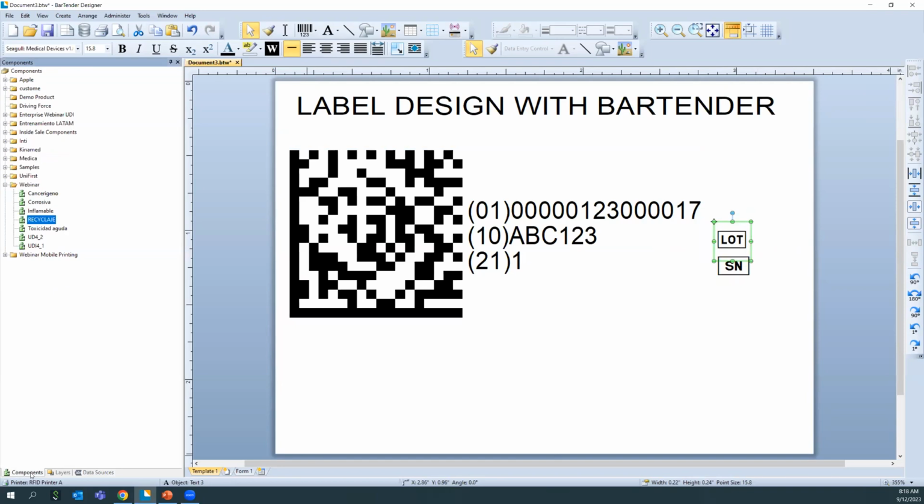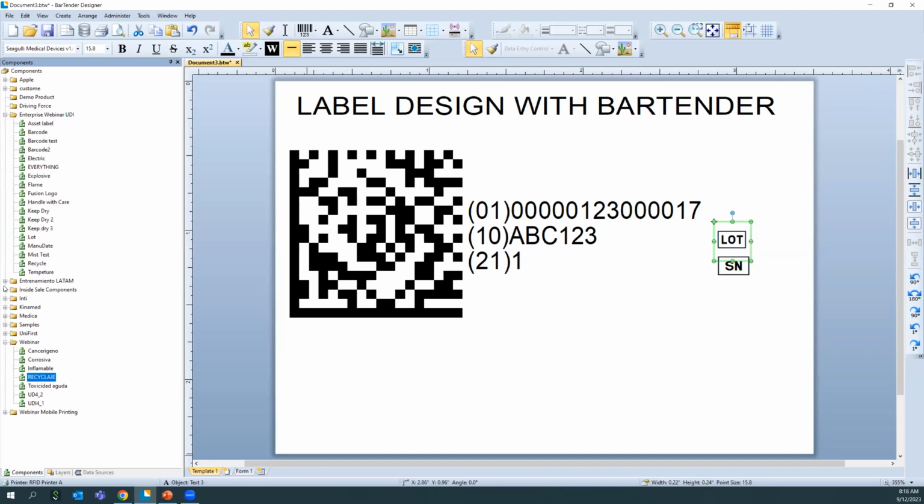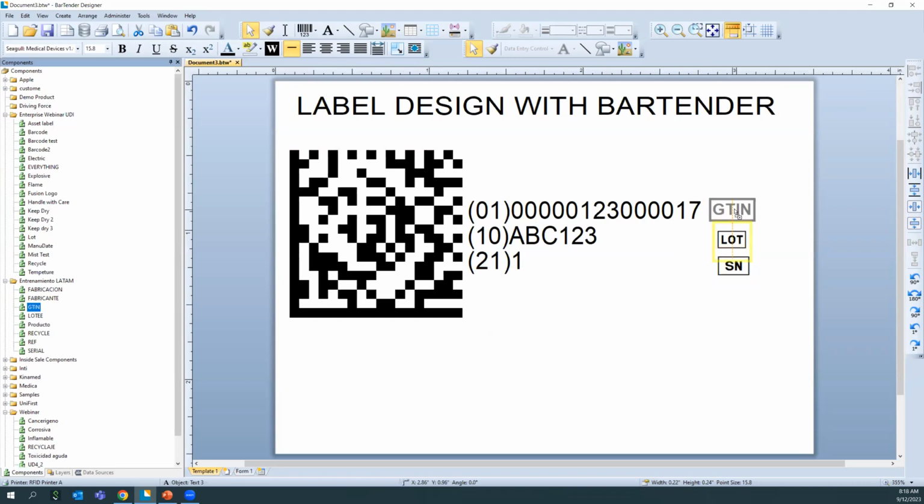Now for this one, I'm going to use something called components. Within my components, there are objects that I'm able to use within BarTender in multiple other labels. So I could use this in another label. And look at the G10. I'm bringing the G10 here. And I know that is my G10. I need to modify that so it matches. I'll do 0.5. And then I will have to shrink it down so it fits.